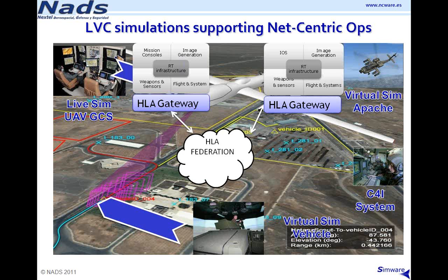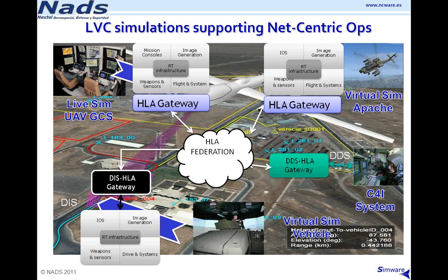It doesn't mean that your simulator has an open architecture like defined in HLA, but that it has a specific component in its proprietary architecture that connects the open API and data model of the HLA federation and its proprietary internals. This is called a gateway, a magic word in simulation that we will use some more. The use of gateways in simulators restricts interoperability capabilities because only a small subset of the simulator's features and data models are translated into the gateway.